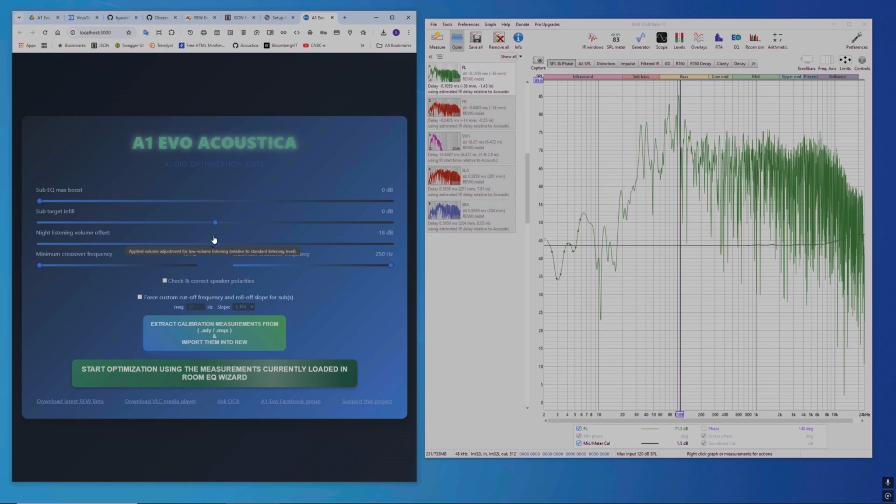This setting will increase bass and high frequency level according to ISO 226 2023 equal loudness contour standards. Very precise, better than dynamic EQ. And you shouldn't turn dynamic EQ on. Just adjust the offset here according to your taste and listening level.